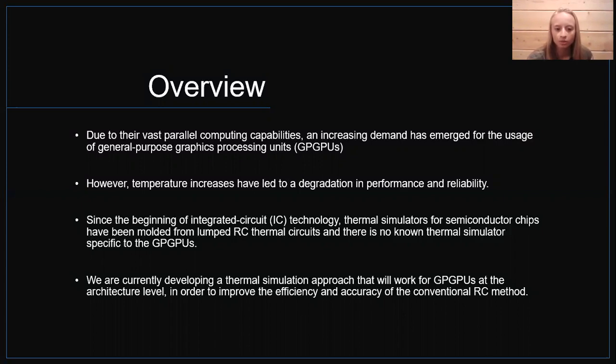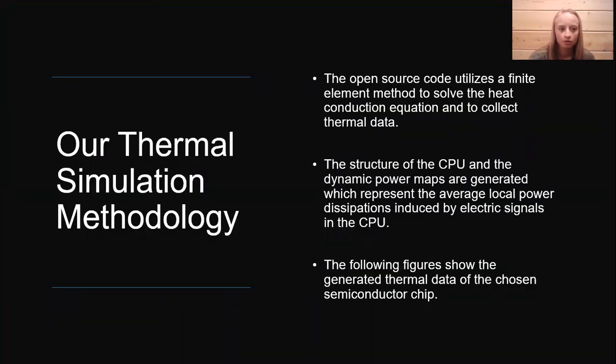We are currently developing a thermal simulation approach that will work for GPUs at the architectural level, in order to improve the efficiency and accuracy of the conventional RC method. Our thermal simulation methodology, the open source code, utilizes the finite element method to solve the heat conduction equation and to collect thermal data. The structure of the GPU and the dynamic power maps are generated, which represent the average local power dissipations induced by electrical signals in the GPU.